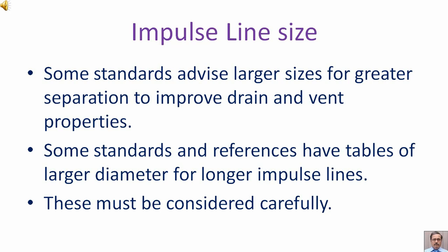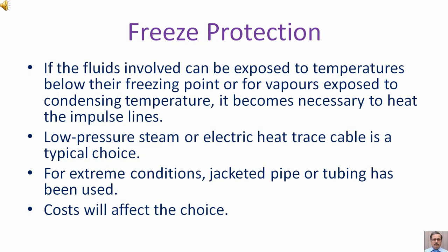Freeze protection. If the fluids involved can be exposed to temperatures below their freezing point, or for vapors exposed to condensing temperature, it becomes necessary to heat the impulse lines.